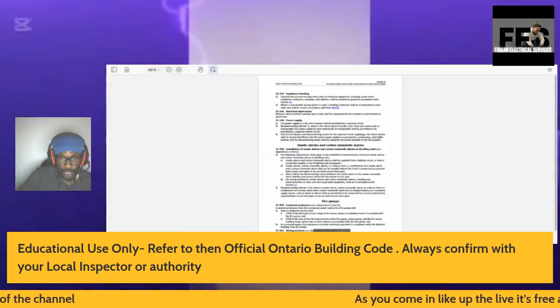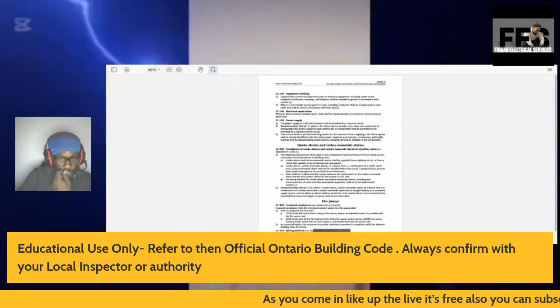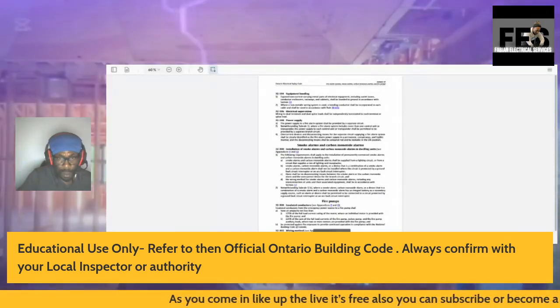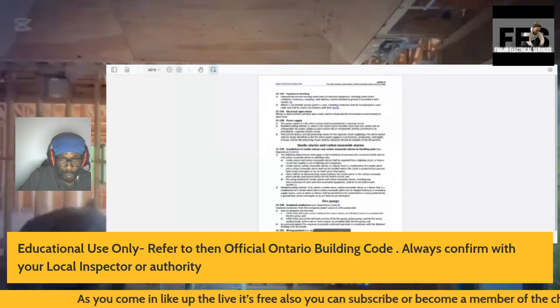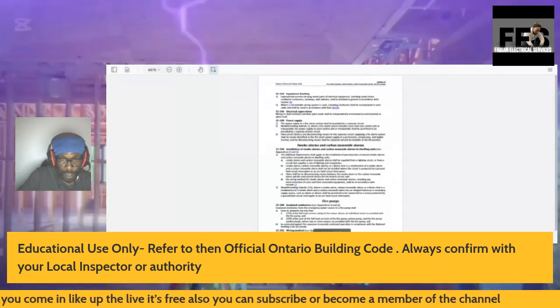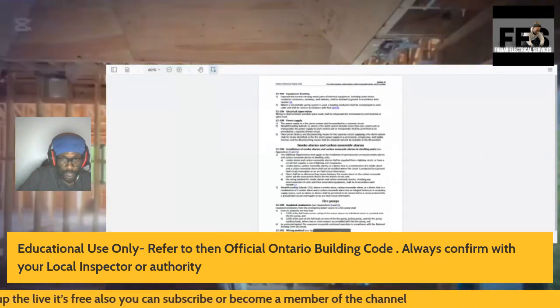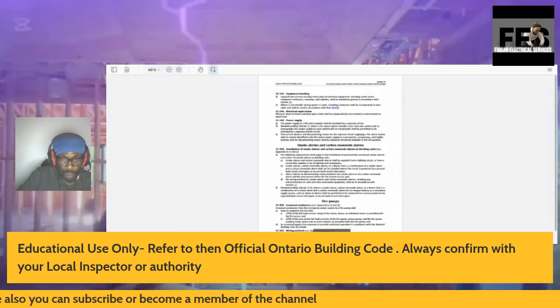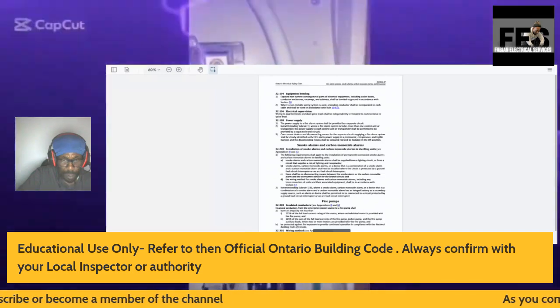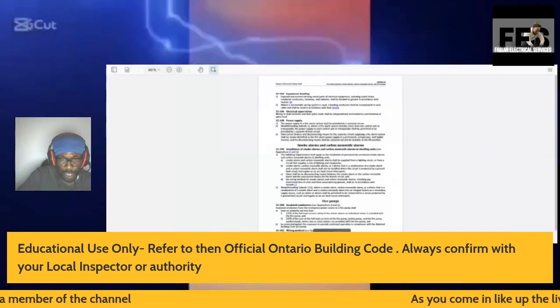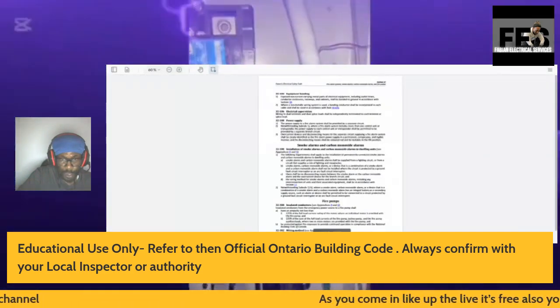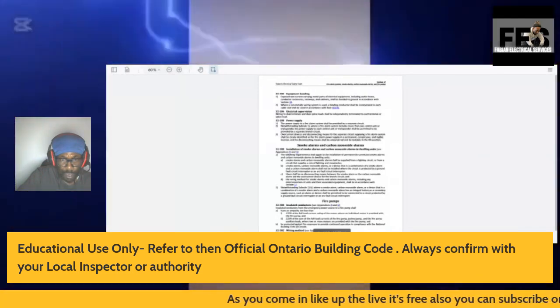Again, the nuisance tripping is going to affect the smoke alarm, and that's probably why they're saying not to install it. I've always pulled my lighting circuit to the smoke detector, so I don't have an issue with this rule here.